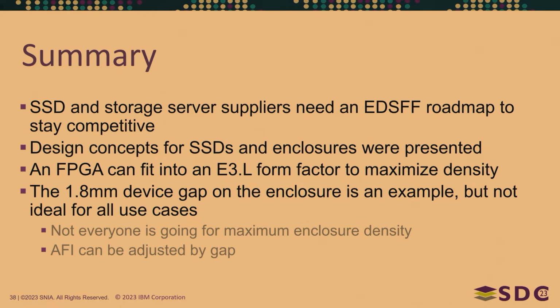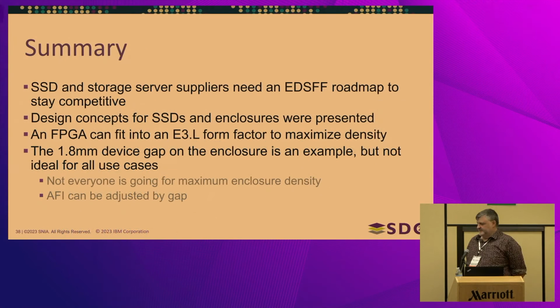And the 1.8 millimeter device gap in this standard is, I find, an example, but not really ideal for all use cases. If you look at the Flash Memory Summit's vendor floor, you'll see a lot of people had designs that didn't have a 1.8 millimeter gap. So not everyone needs that gap for maximum enclosure density. You may have some more compute-focused servers with less storage in the front. And if you need to, you can adjust the airflow impedance by adjusting the gap. So that's another knob that you can turn.